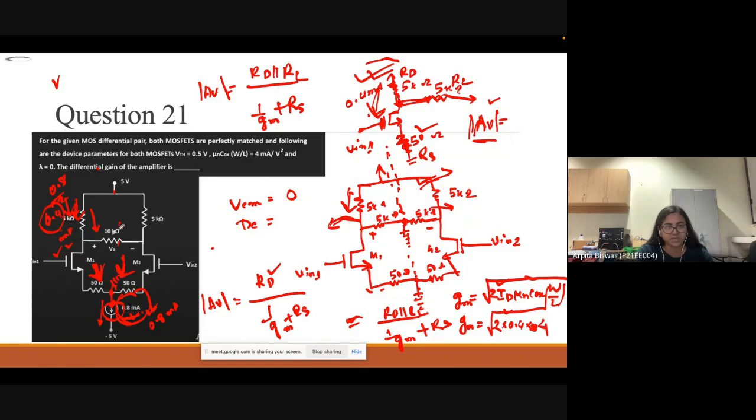What we have done here is divide this 10 kilo ohm resistance in series as 5 and 5. So you can see this side and this side look the same. In that case we can take it as half symmetry, and we take just one part, since the gain is the same on both sides.